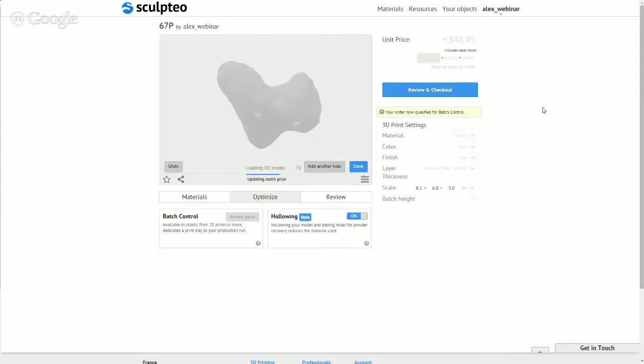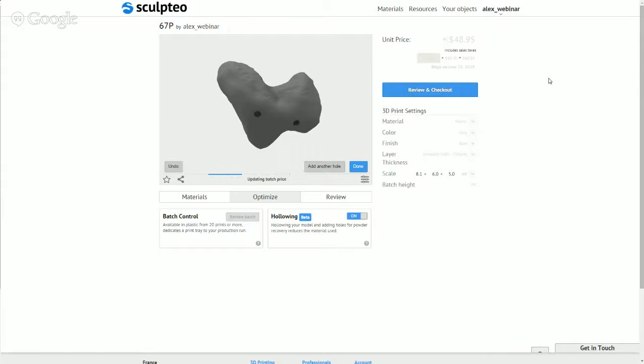I'm going to print a batch now and see if that saves us more. It's not a very efficient model for batches because it's got all these hollow spaces here, but we should save another 5 or 10%. Just let this think. So yes, we saved another 10% here. So you can add optimizations together, and that all adds together. So you shouldn't hesitate to use these optimizations.